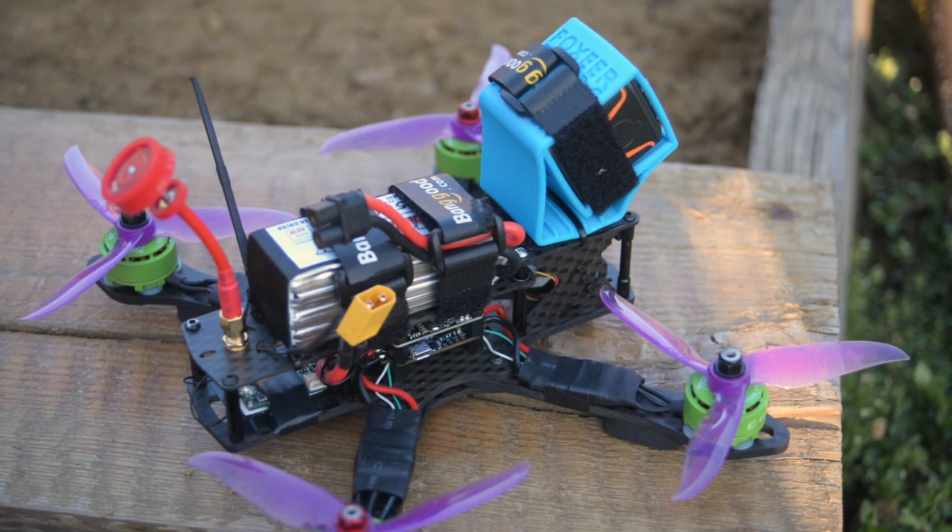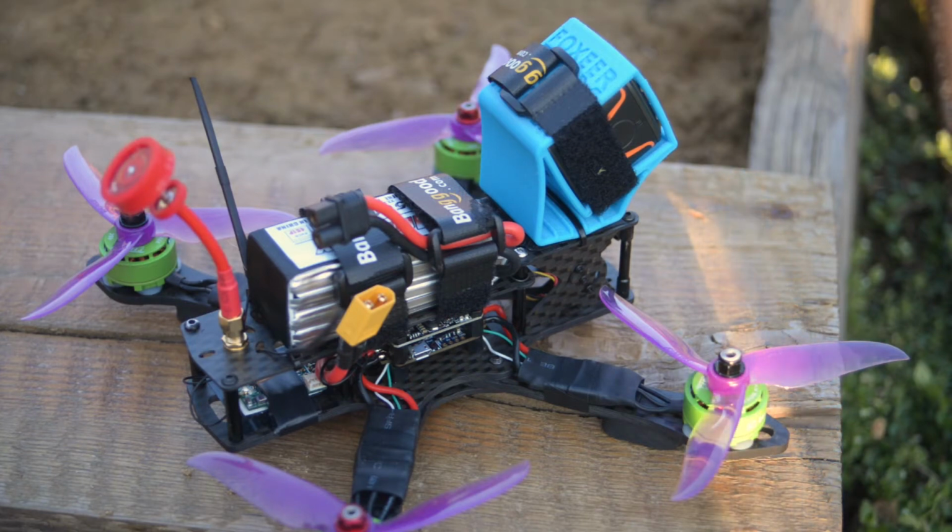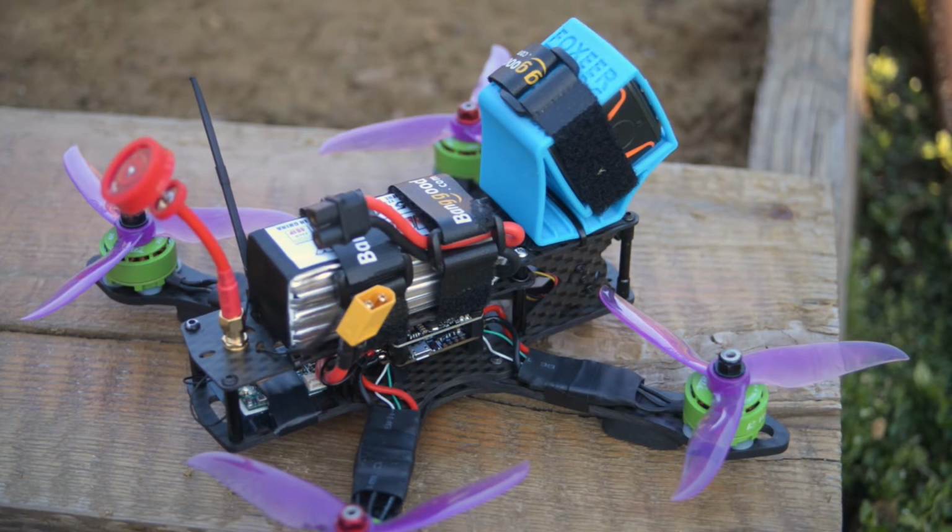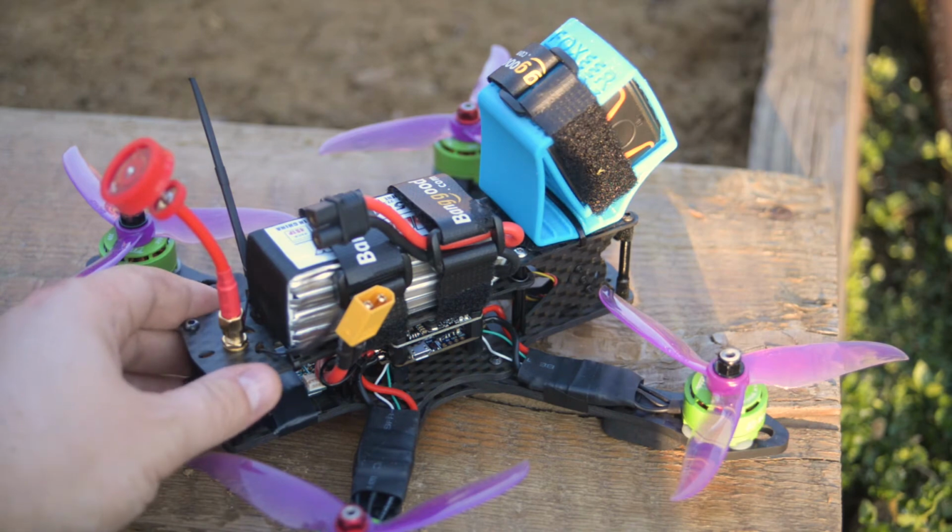This is how the final product looks. For the camera, I'm using the printed flexible mount, which is held on by Velcro, and the camera is fixed by a Velcro strap. The antennas from the receiver I mounted into heat-shrink tubes supported by a zip tie. This is the classic approach, I think.